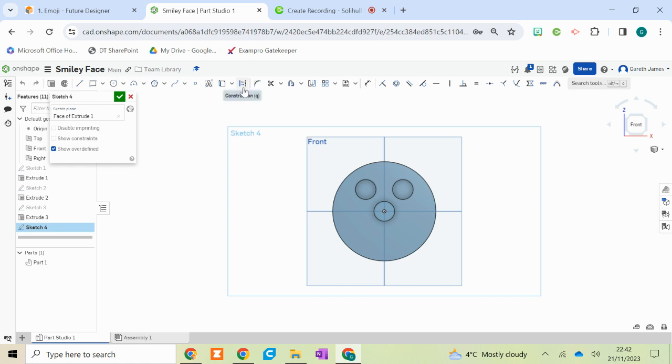So you'll notice up here the construction line. So I'm going to select the line, and then I'm going to hit this option. And notice that both icons are selected. I'm going to go to the origin, and I'm going to draw a nice long line down here so you can see that I now have a dotted line. That is there as a guide. It's there to help me construct the next part of my drawing.